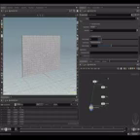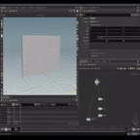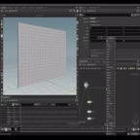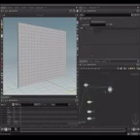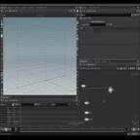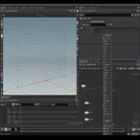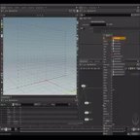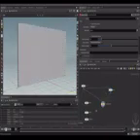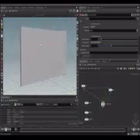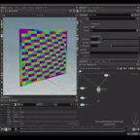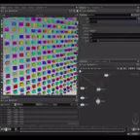Another cool trick is to Voronoi fracture this geometry using its own points. And we can get some interesting regular patterns from this. So let's add an add node, and I'm going to delete everything but the points, so we can use them to generate the cells. So let's drop down a Voronoi fracture, set the connections, and if I visualize these pieces, I'm getting this interesting brick kind of pattern. So let's explode view this, and here we go.